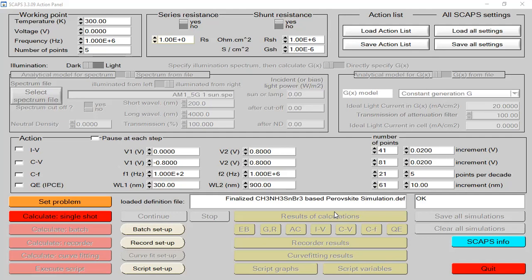Nyquist plotting and graphical representation is one of the most important methodologies that can be used to extract EIS data commonly, and we can vary the input signal over a range of frequencies and compute its effect on the impedance of our perovskite device. So I just explained what EIS is, and how we can extract EIS data, by which technique: the Nyquist plot.